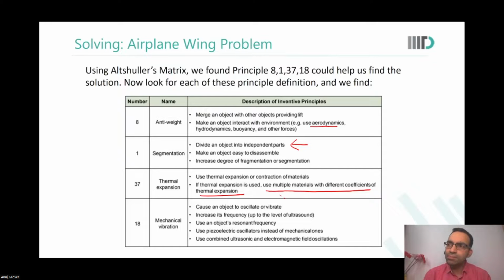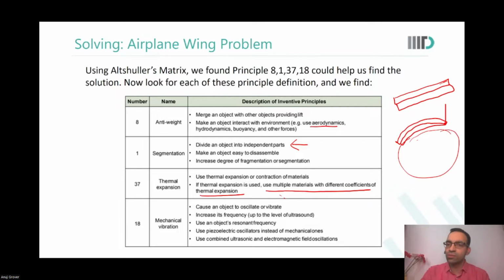In one of the office hours, we talked about bimetals. Remember, where we said two metals are pasted together. Each has a different coefficient of thermal expansion. As the temperature increases, let us say the top metal expands more, the lower one less. What happens? Your material becomes like a curved thing. So you have more surface area inside. The pressure inside your chamber could reduce.